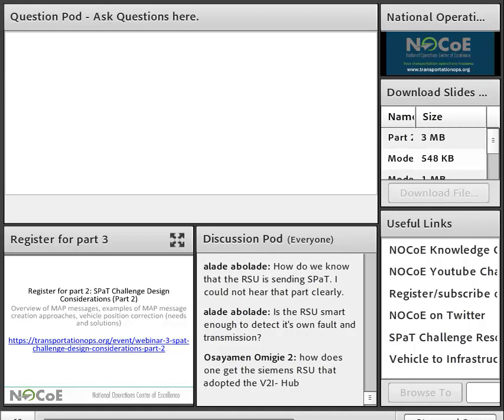Some of the controller vendors have started to make marketing arrangements, if you will, with some of the DSRC vendors. So the thing you should do is talk to your controller vendor and see if they have worked out some arrangements with certain DSRC vendors for their equipment to work together. That's probably the best step. There's a broad number of combinations of equipment out there. We've got both Intelight and Econolite controllers, and we have DSRC units from 4 different vendors on our system that we've made work. So there's a broad realm of possibilities.